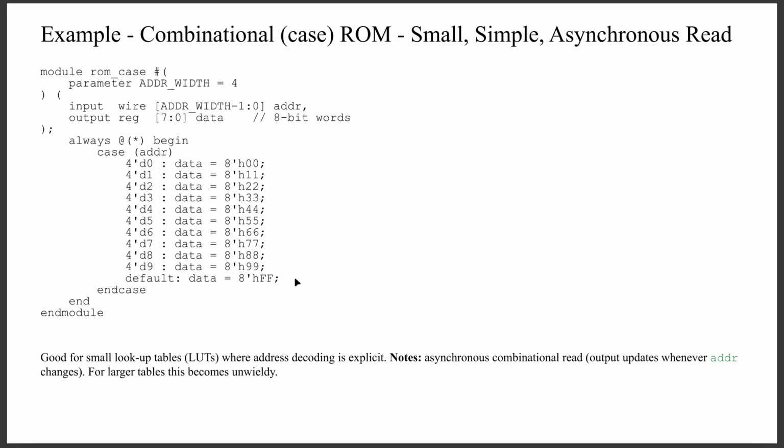This is good for small lookup tables where address decoding is explicit. Notes: asynchronous combinational read, output updates whenever address changes. For larger tables, this becomes unwieldy.